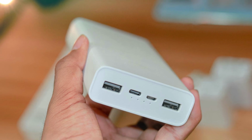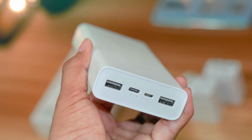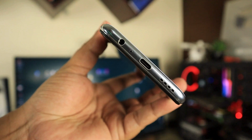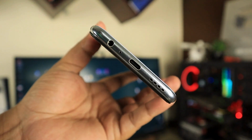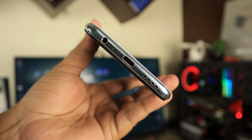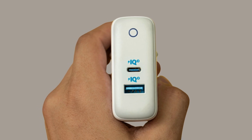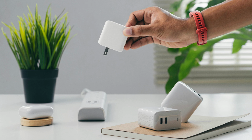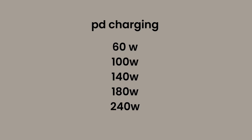No. Okay, so first of all, in smartphones, almost every manufacturer has their own proprietary charging. But there are some standards like Power Delivery and Quick Charge that are present in some phones, but Power Delivery is more mainstream adopted. It has different versions, but it is rather easy, as it is written on the cable packaging if it supports PD charging or not, and wattage is written on it, for example 60 watts, 100 watts, 140 watts, 180 watts, 240 watts, etc.